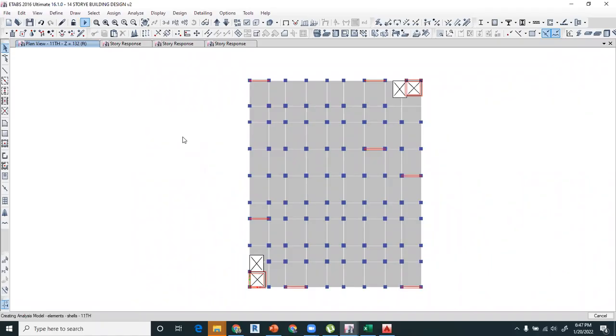Sir, we did many shear walls, so can we make only one or two shear walls? How to afford it economically? Is only two walls enough? It's not enough. It depends upon the geometry of your building. If it is controlling your demand with one wall or two walls, you can do that. But if it's not controlling, then you have to force the architect to give more locations so I can give more shear walls, right?